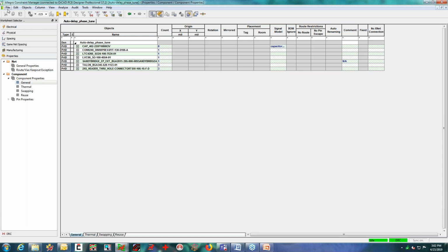Any route barrier will be looking at copper features. So if it's a pre-poured copper plane, maybe it's on a specific layer and maybe you ban the routing above it on the next adjacent layer or below it on the next adjacent layer. But if you have copper pour inside of a route barrier, you will be flagged with a DRC.